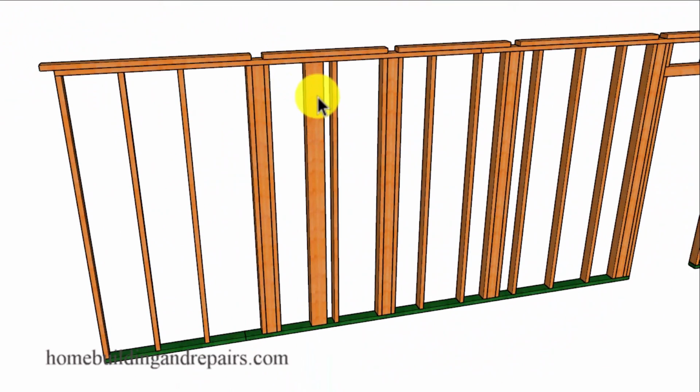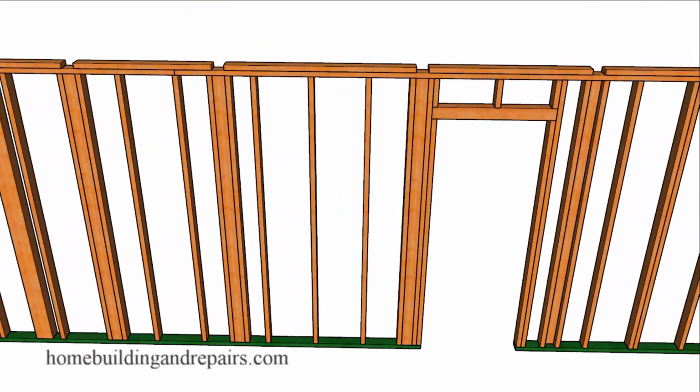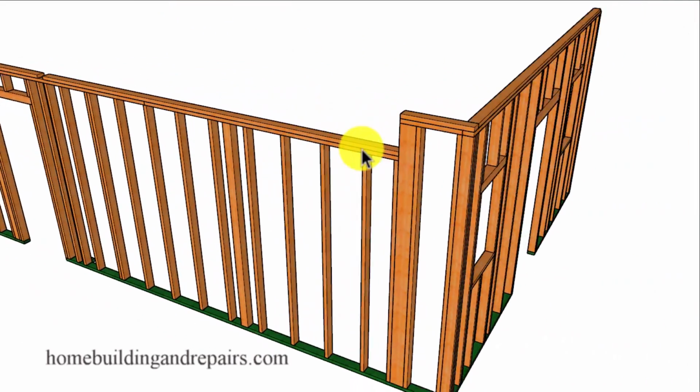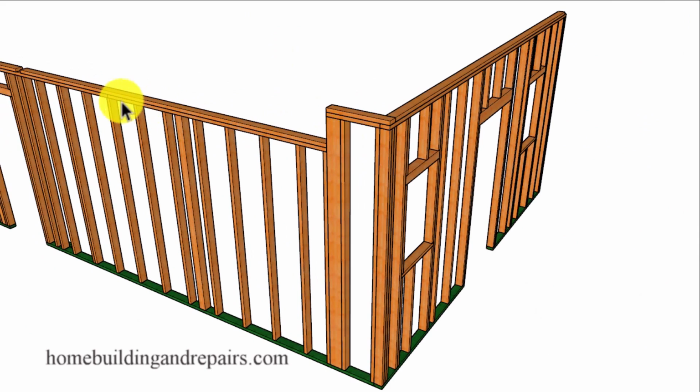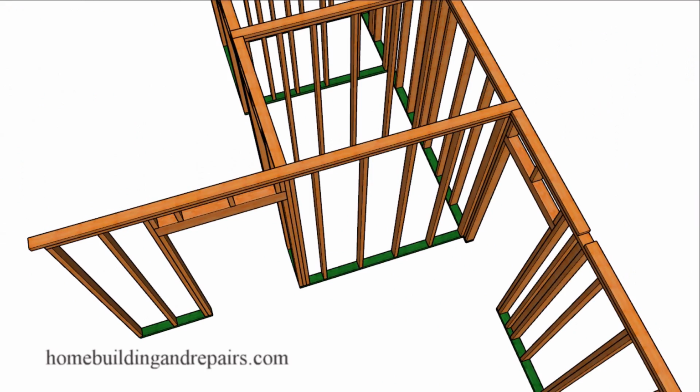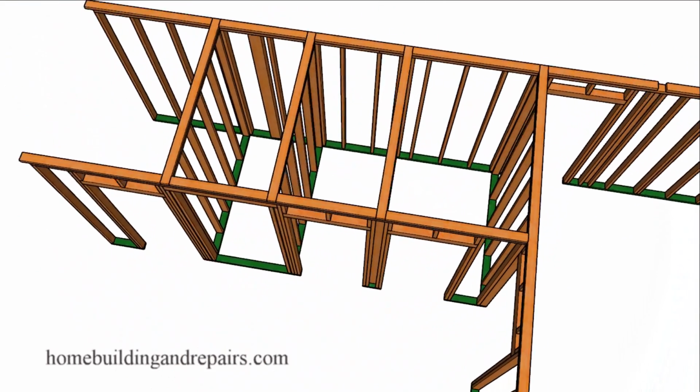And a large post. This post here is going to be supporting a lot of weight and will definitely require some type of a structural footing underneath it. And of course, our channels here where we will be intersecting additional interior walls into this long wall. And in this long wall, we will have another supporting post along with a post over here that will be supporting floor beams above. Let's go ahead and take a look at the walls located in our master bathroom.